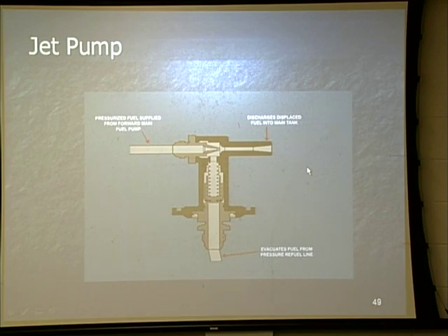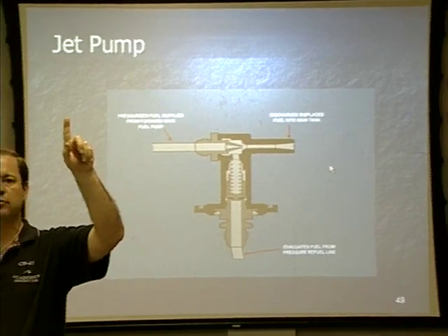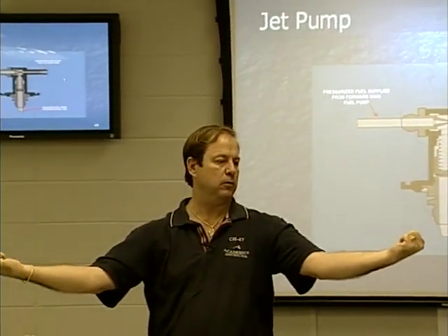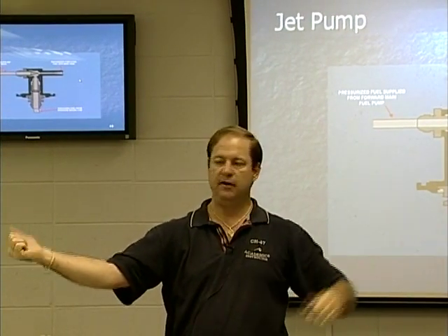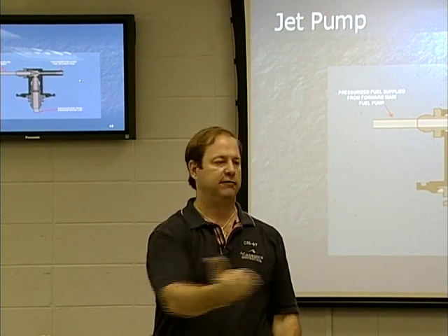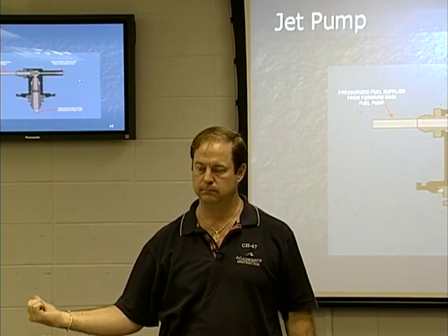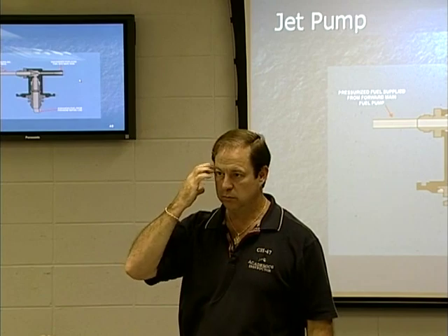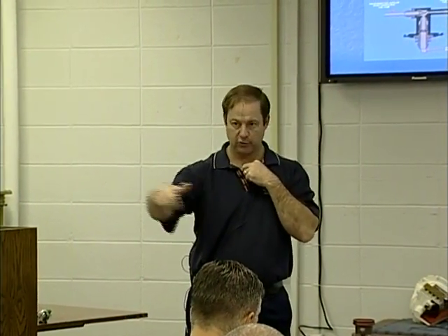So basically what we're doing is, as long as we turn on both forward main pumps, we're evacuating that fuel in both directions. If I just turned on one pump, it would still evacuate that line. It's only for internal use, only for this use. It does no other purpose. The two forward pumps are only to evacuate the fuel line? No. It's also going to pressure fuel to the tank. But this process, this jet pump, is only connected to the forward pump.